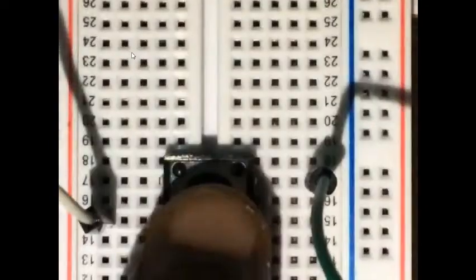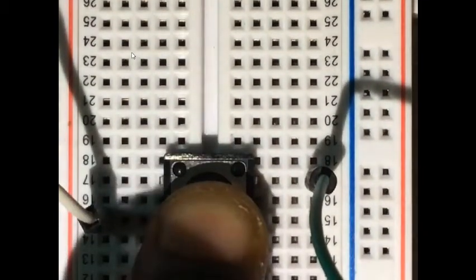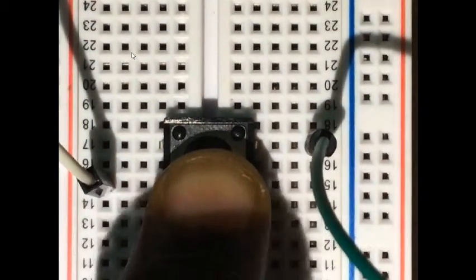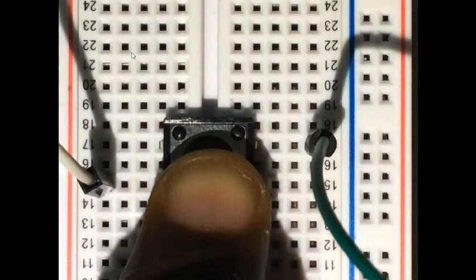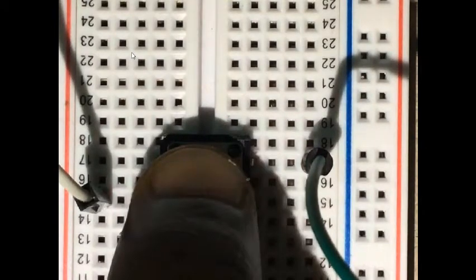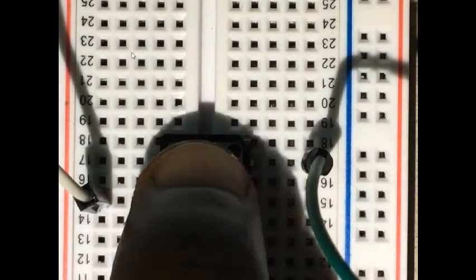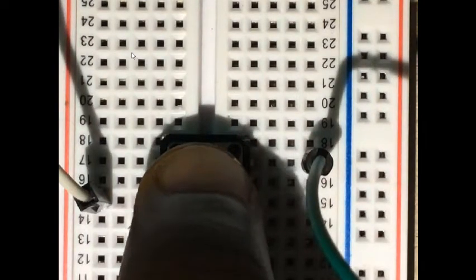When I press the button and I hold it, it connects both. It connects all the legs of the button together electrically inside it. So that means that both of these jumper wires are now connected. Let me explain again. When I press the button like this, I'm pressing the button now, it connects all the legs of the button together electrically. That means that both of these jumper wires are now connected together with the way I have connected them.